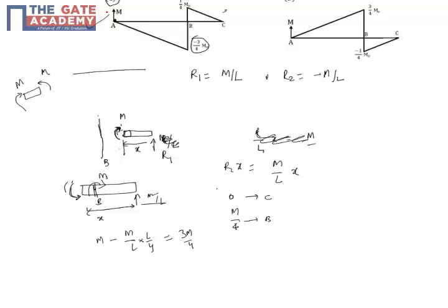Always, when you are asked to find the appropriate bending moment diagram, remember one thing: get the reactions first. If it is a concentrated load, in the bending moment diagram you will see straight lines and a triangular kind of structure. Because of a concentrated moment there will be a sudden change in the bending moment. All these facts you can get from taking a section.